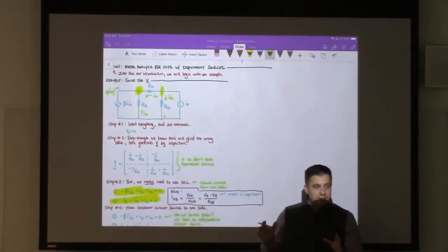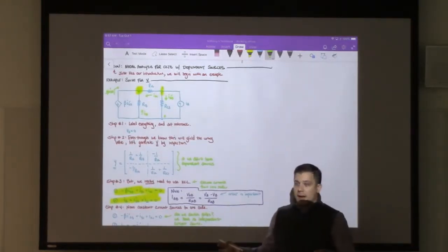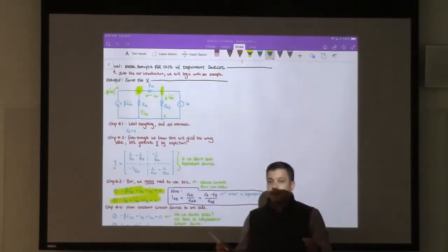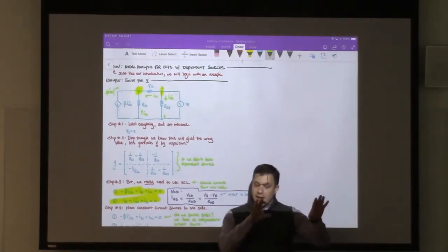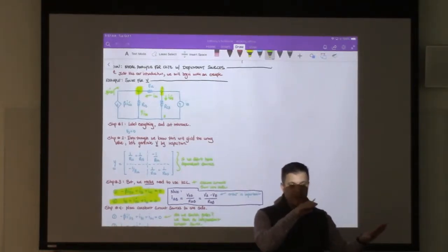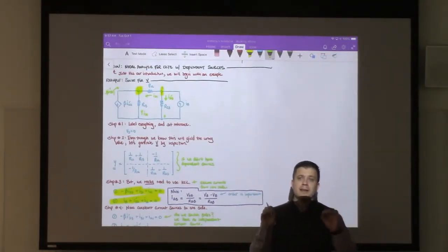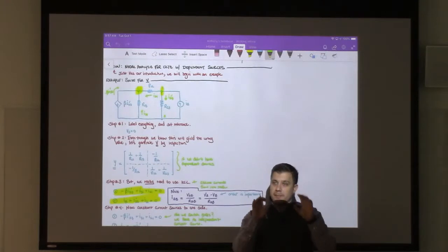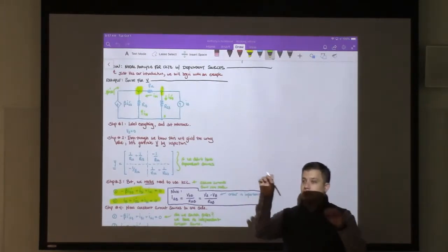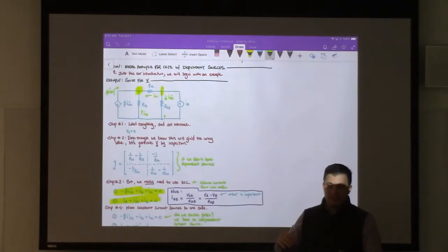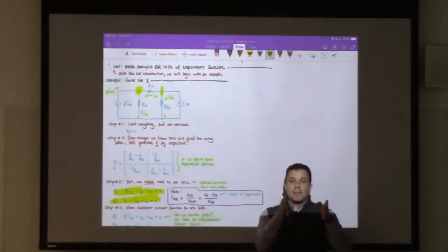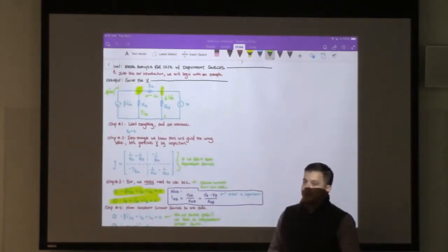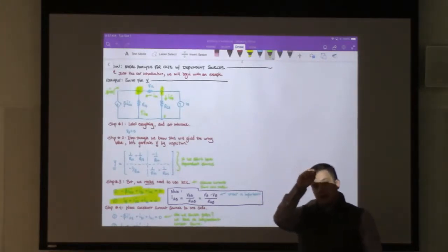The admittance matrix has two different types of elements: the diagonals and the off diagonals. If we keep all of our signs consistent with what we did in the example, the diagonal elements are positive, and they represent a sum of all the admittances connected to that node. Remember, admittance is 1 over resistance. So we've been representing it as the sum of 1 over R_ik, and you look at all the adjacent resistors. You do that going along the diagonal.